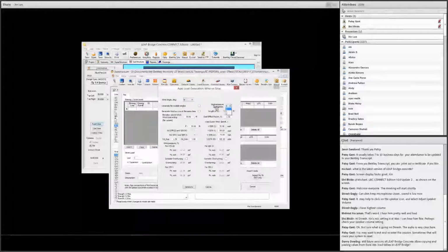So this is a newly added wind exposure category. So we can choose it's C. Then we input the other input fields. This is for the elevation and the C sub D for superstructure, substructure, and this is some other parameters for different limit states. This is automatically calculated based on the wind exposure categories. So we can use this as a default. A user can also override these values as well, if we want. Include at the bottom part.